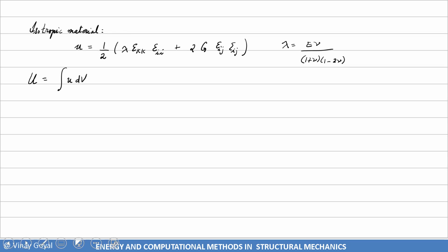Now, that is for a simple linear model. You could have a nonlinear elastic model. That's fine. You can have a completely nonlinear elastic model, but you'll have to do this integral to get the total strain energy. So for example, let's do a one-dimensional example. Say the stress for a nonlinear elastic material, and I told you stress was E times epsilon to the 1/2, which is going to look a lot like this.